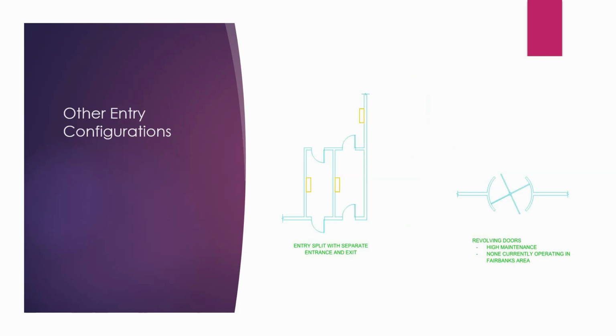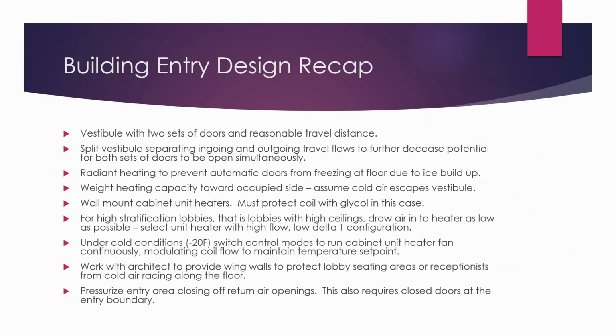And so then the last picture here is a set of revolving doors. And I just wanted to show this. And you see these, and they seem to work. I've seen them in Calgary, and they seem to work. But I will say that there are no revolving door examples used in Fairbanks. In a few places where they have been used, they've been pulled out. And I'm not sure personally why that is. I'm guessing that they simply can't keep them working in cold weather, that they tend to ice up. But anyway, that's our experience with revolving doors.